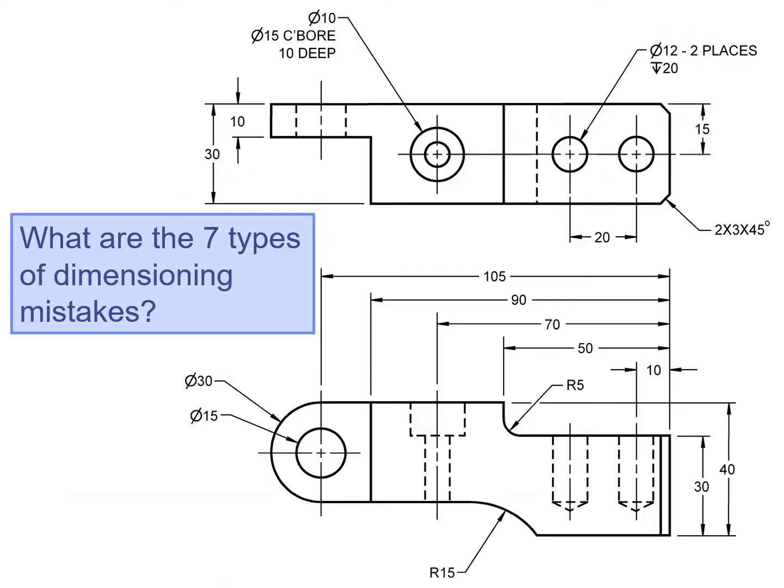Next slide. Let's practice our drafting again, how to place and call out dimensions, or how to correctly label dimensions and use symbols. Right off the bat, we can see that we should avoid using words. This was acceptable 50, 60 years ago, but in the last few decades we got away from using words. Instead of counterbore, we'll use the U shape to define a counterbore hole. So here we have a counterbore hole. And for the depth, instead of using the word, we're going to use the downward arrow.